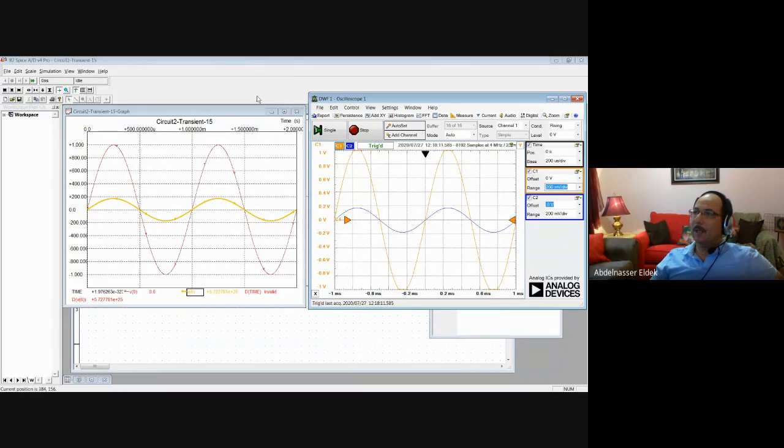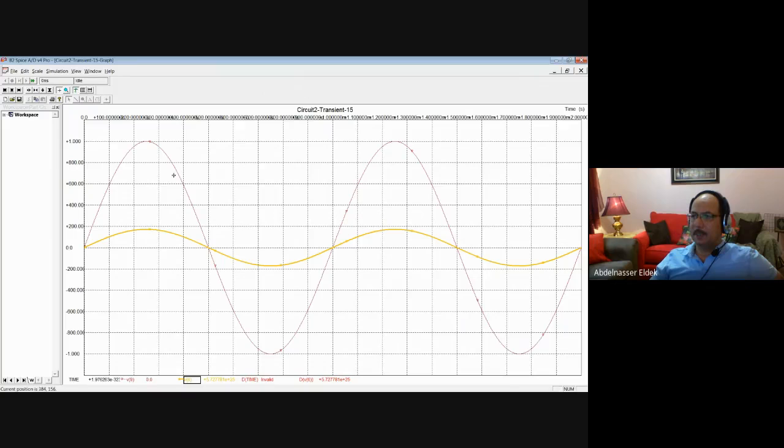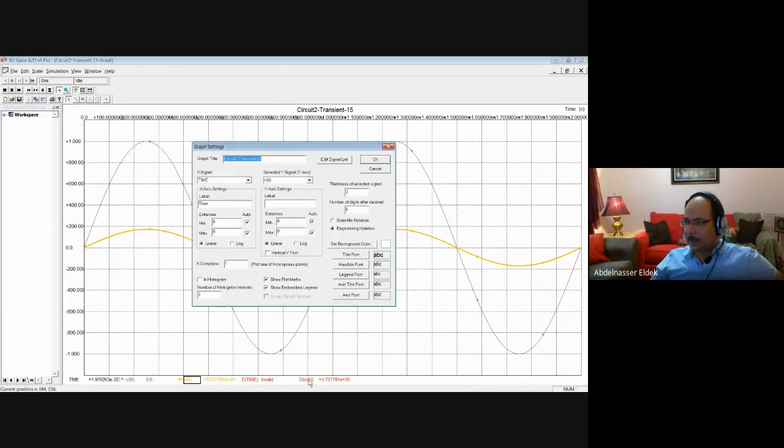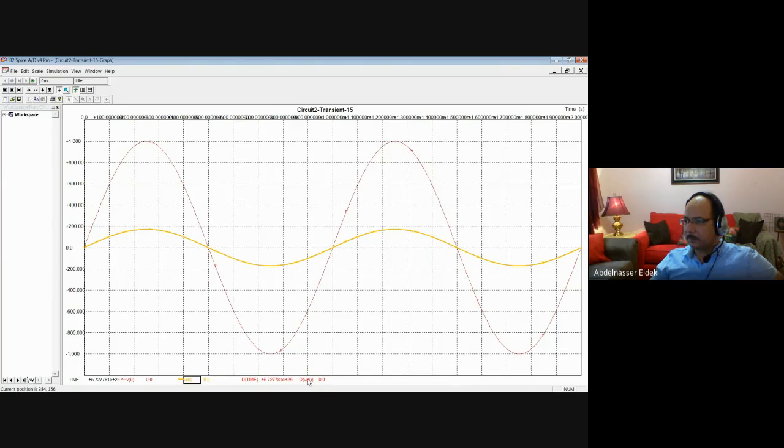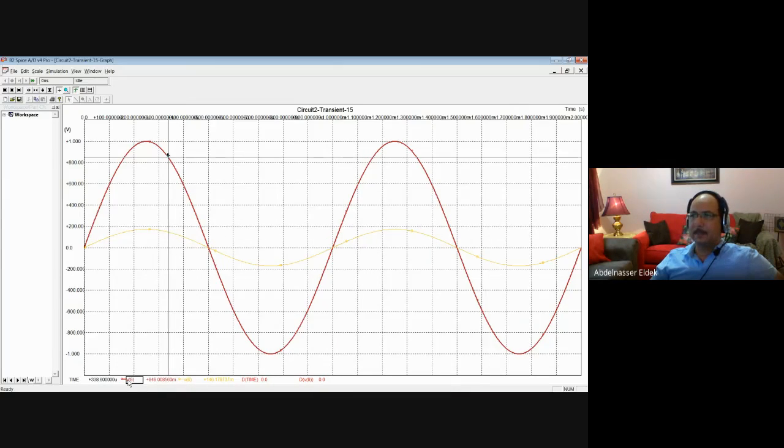Okay. Now, if I want to check in B2Spice what the amplitude is, for example, you need to select here. You have two signals here. This one is the red, and this is the orange. So the red, if you want to know, for example, the maximum here, you go to the maximum and click it. Okay, and now you can display the minimum. The value is 999.96 millivolt, which is almost 1 volt.